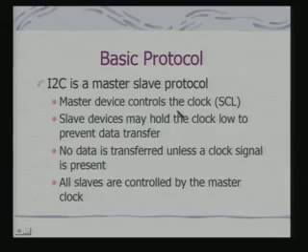Obviously, this implementation would require a kind of wired AND connection. In fact, all these interface lines are open collector or open drain connections.